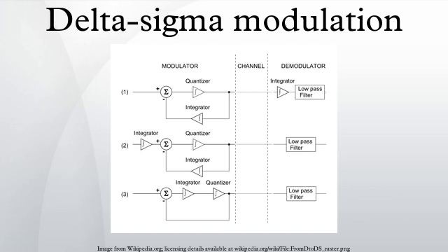Relationship to delta modulation. Delta-sigma modulation is inspired by delta modulation, as shown in Fig. A2. If quantization were homogeneous, the following would be a sufficient derivation of the equivalence of DM and SDM. Start with a block diagram of a delta modulator demodulator.